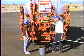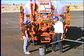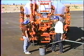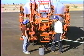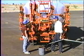So if you're in a situation where you know they're going to test and it's paving grade asphalt, then you have to be very careful about how you handle this flushing thing. And that holds true with the whole flushing project on the truck. And really what it gets down to is knowing when to take your sample and where to take it.